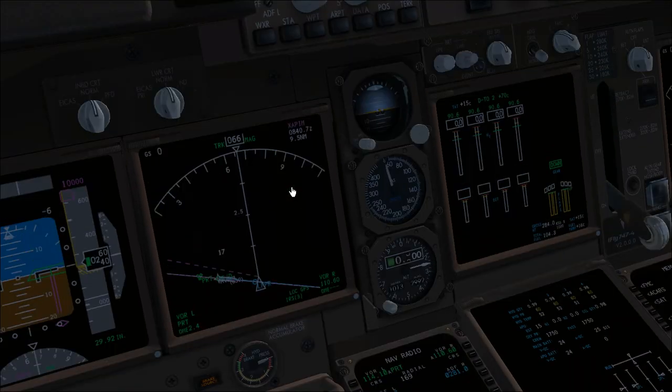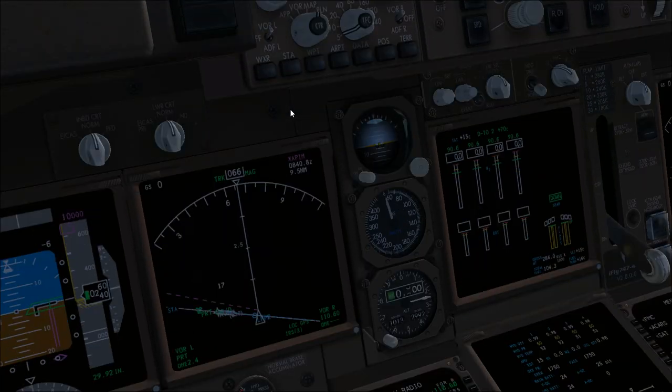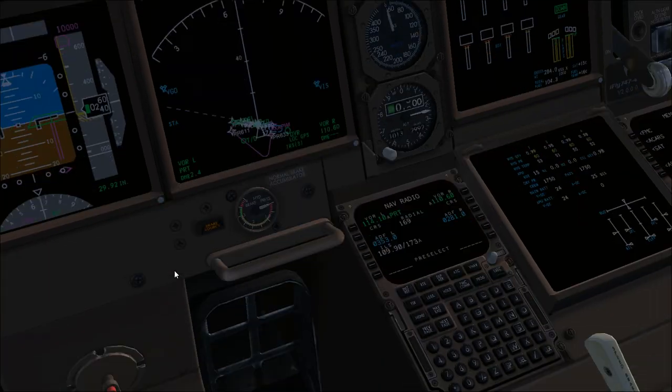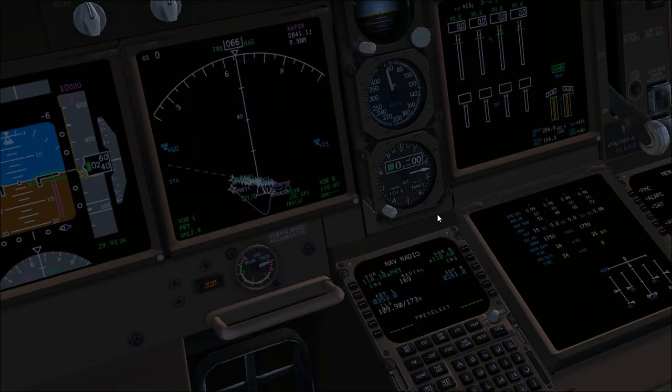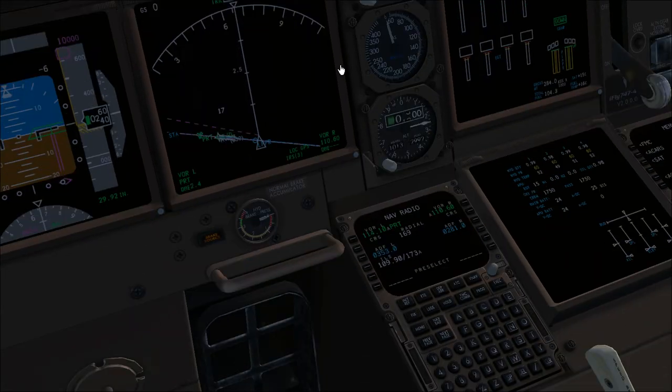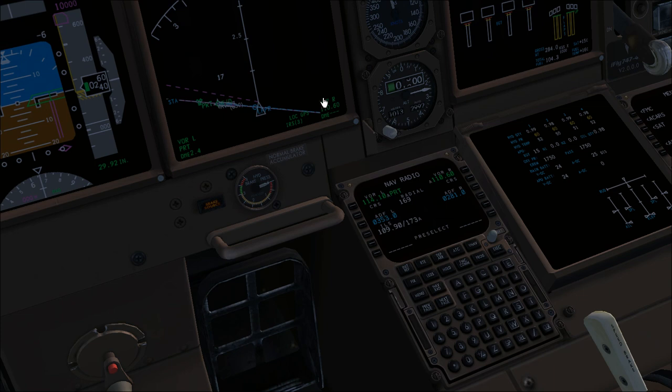In this case, for example, if we go and select stations, we can select another VOR, for example. We have Victor Golf Oscar. We can go down here selecting Victor Golf Oscar and maybe inserting in the second radio, and as you can see it is manually tuned. If you want to retune to automatic, you just press delete, and this retunes to 110.60. Now we can retune to 05, and this actually completes our overview of the pages.